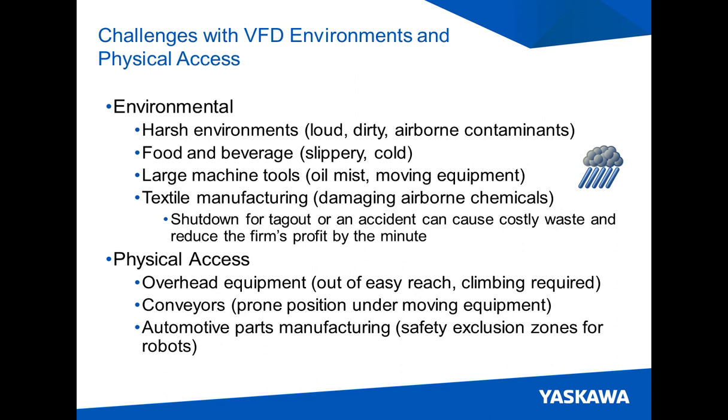Another example might be a textile manufacturer. They could have airborne chemicals or finishes that, if you open up an enclosure where a VFD is installed and you let those airborne things into the cabinet, could potentially damage these sensitive circuit boards if the VFD is left for extended periods of time. And that's why a lot of firms will install a VFD inside of a protective enclosure that's suited for the environment that VFD is in.